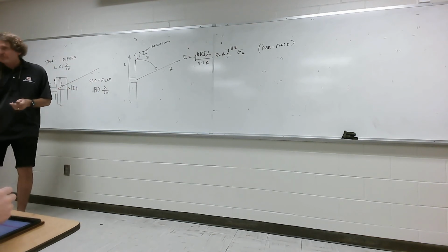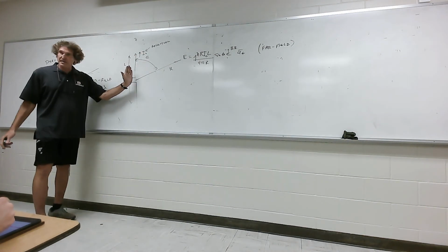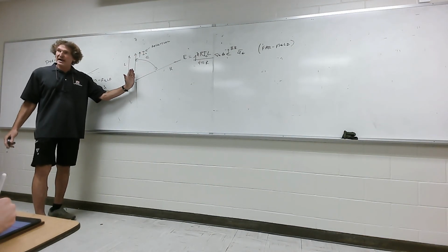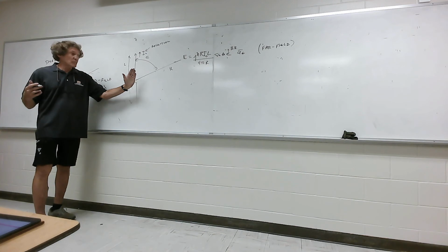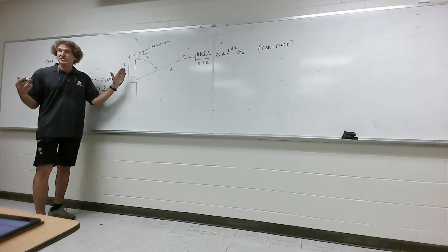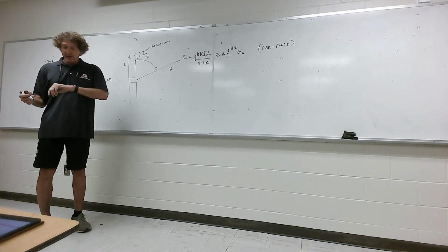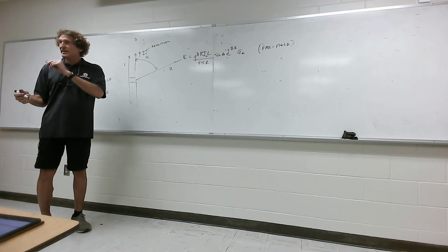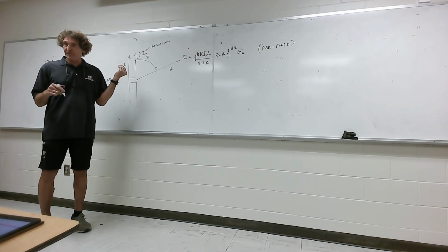So what is the far field? Basically, if you're real close to an antenna, doesn't matter the type, you're going to have capacitive energies. You're going to have an electrostatic field around it that will decay back when you actually shut the thing off. That's an electrostatic energy that collapses back, just like a capacitor. You're going to have magnetostatic energy too that would collapse back. That's near field energies. Do y'all follow me?